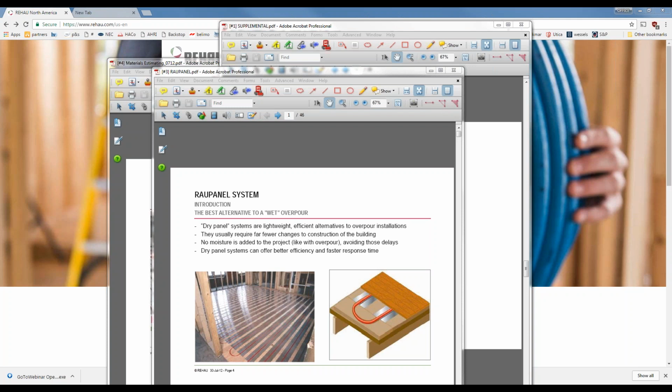One of the main advantages of the aluminum heating panels is that they help disperse the heat through the subfloor. They obviously do improve the heat transfer in general, but versus having the tube just stapled to the bottom, where it can create a temperature gradient in certain situations from the flooring on the top, the aluminum panels really help disperse that, so they do need to be up against the floor. If you weren't going to be able to do that because of nails or whatnot, I would just recommend skipping the panels and doing the tubing directly to the subfloor, because if you start pulling it away from that subfloor, it's just going to lose its effectiveness.